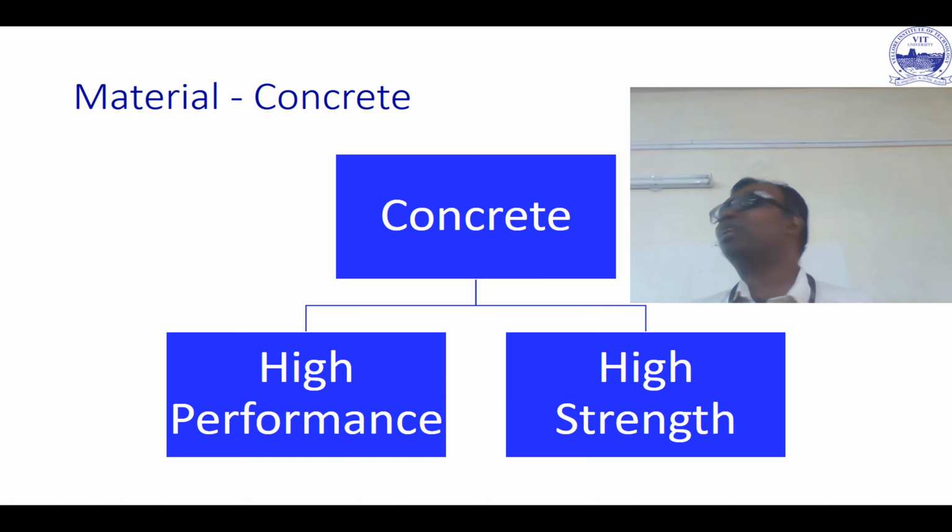Okay, any idea how drying shrinkage can be reduced? Yes, here steam curing is done. It's kept in a moist environment, so drying shrinkage is automatically reduced. Again, the water content is very, very less, so the amount of water which can evaporate from the matrix itself is reduced. So there's again no chance of drying shrinkage actually happening. You're just reducing some of the things.